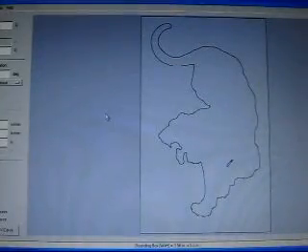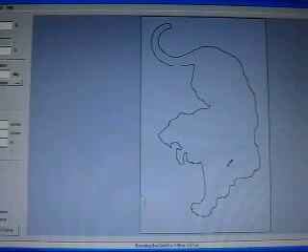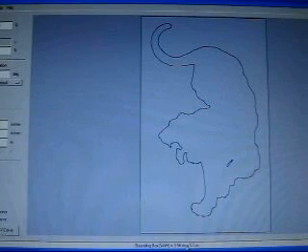So what we're going to do is go ahead and open up our DXF file with this program, because this is going to be our first machining operation. We're going to use the 1/4 inch tool to cut around that thing. So we open up our DXF, and there it is. Now you'll notice it has been sized by Inkscape appropriately. You notice on the bottom of the screen it'll give you the dimensions.